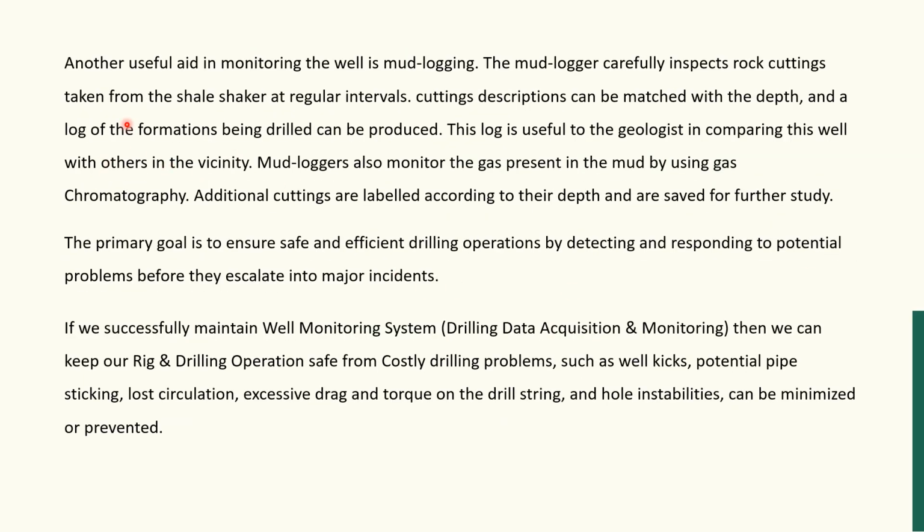Another useful aid in monitoring the well is mud logging. The mud logger's role is very important. The mud logger is stationed on the drilling rig. He carefully inspects the rock cuttings, taking them from the shale shaker at regular intervals. The cuttings description can be matched with the depth.